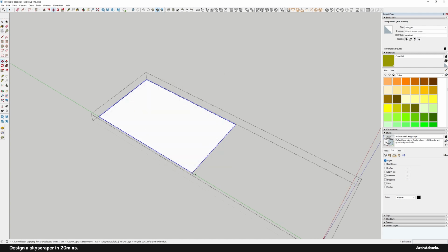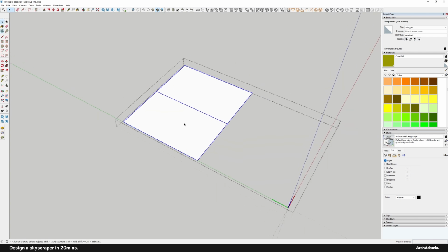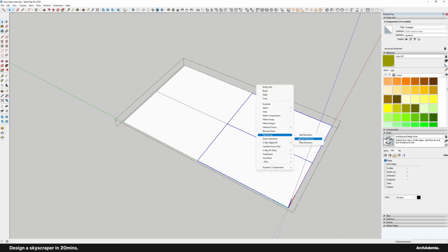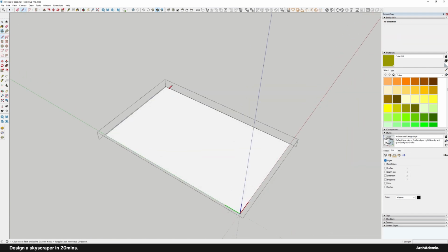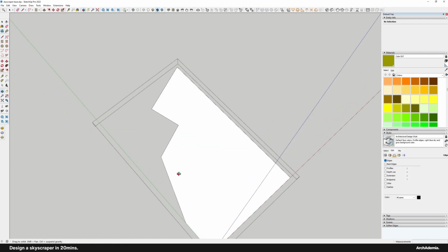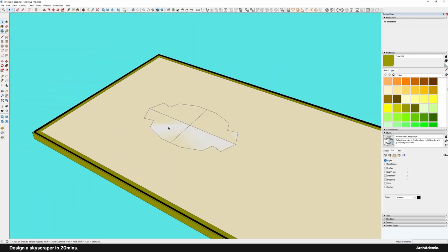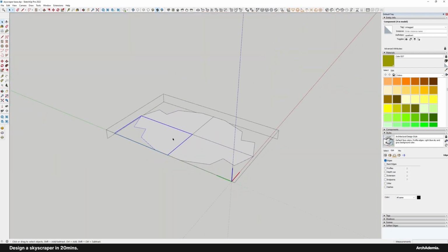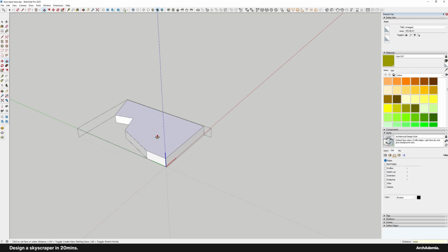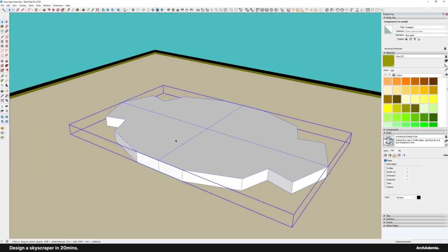Just give it any name you want, really. Make sure you're flipping it along the end, the direction in which you copied it. And then all you need to do is just something that's quite interesting. Now, of course, you need to consider how this impacts your floor plan. This is just trying to get across a nice, simple concept. Typically, it's 3 meters for your floor to floor.